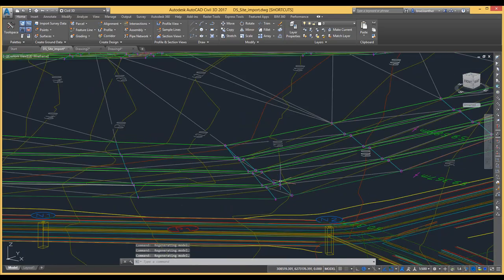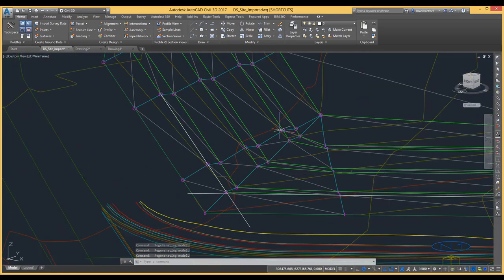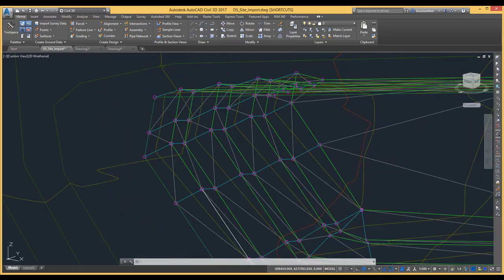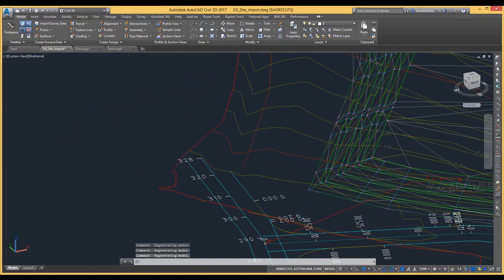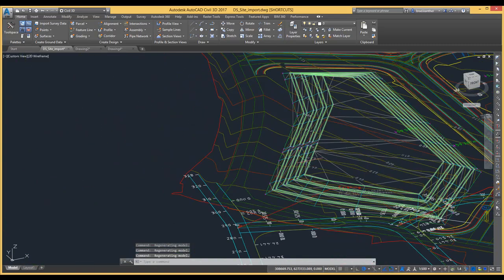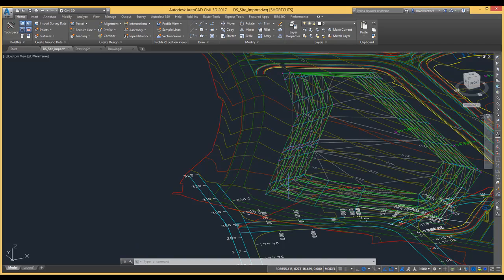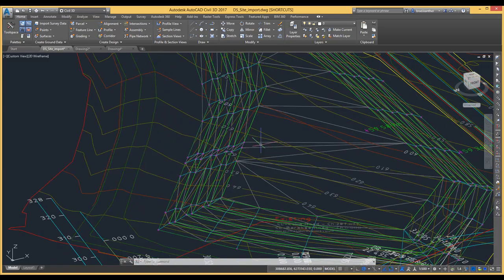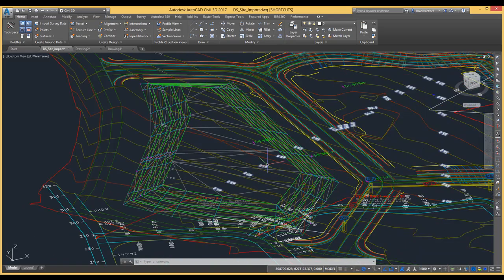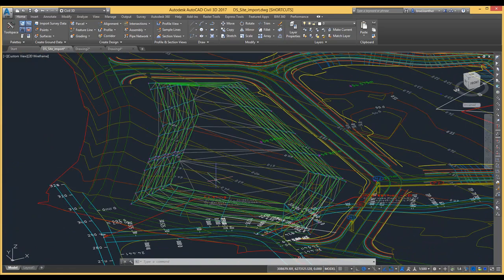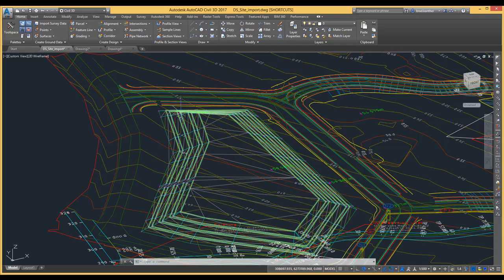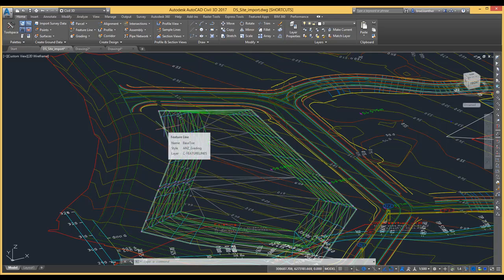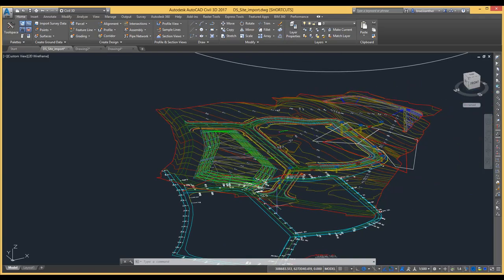So you can see a subtle turn in the corner like that looks actually quite nice, but big sharp corners with significant grade changes look a little bit jutted and don't really give you probably the result you would get if you were to create that manually. So you're probably going to find more limitations as you work with these more. I'm just trying to highlight some of the general ones that you're going to notice straight off the top of the hat. I've tried to do this with a stockpile, but obviously this has uses for developing car parks, small pads, and other sort of complex site gradings around your projects.